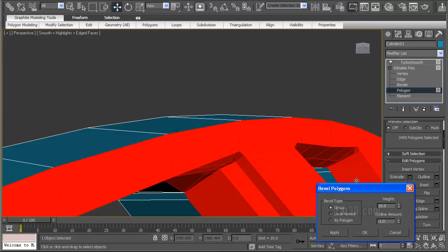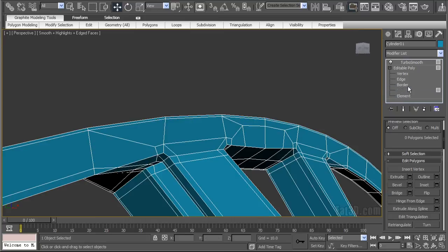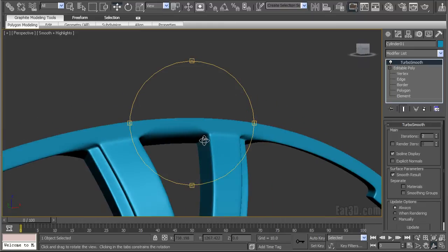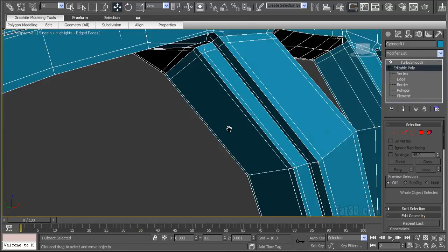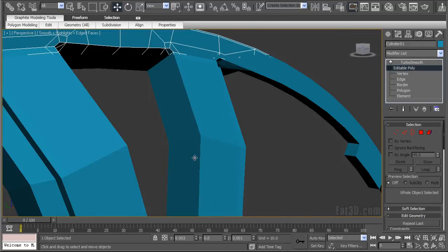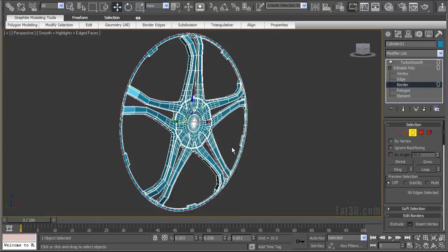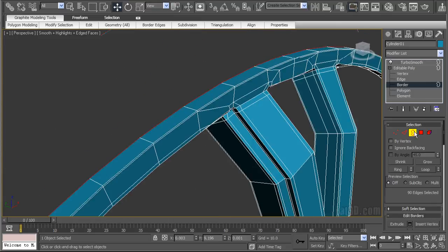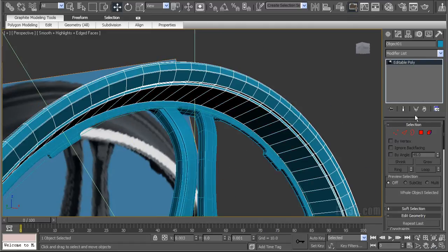Select everything on the mesh, choose bevel, and do just a little bit. What this did was it basically made the chamfer for us around every edge. Like on the inside, it doesn't really matter because we're not modifying it and you can't really notice the chamfer. But out here, we don't have to worry about it anymore. So extrude it in. And there we have that.